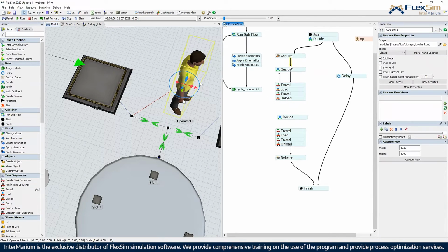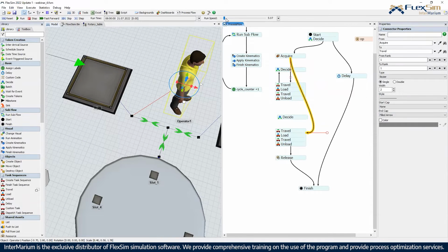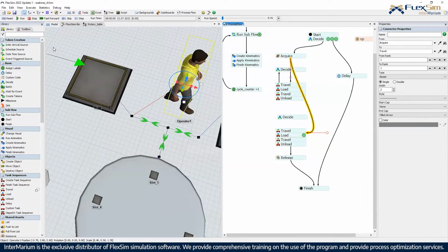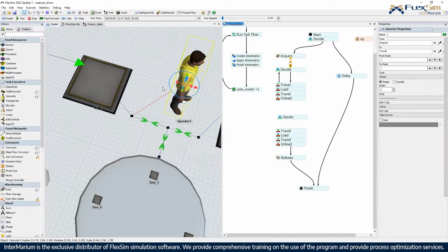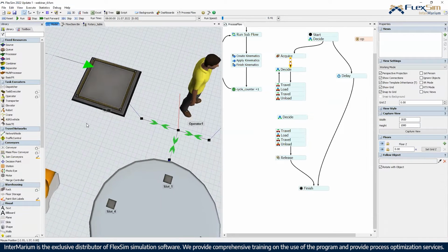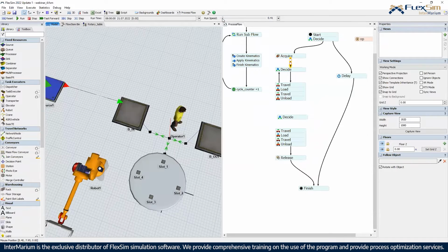Why? Because FlexSim assumes that operator is already there and this logic runs faster than the model. So this is first before the simulation. So when I run this logic, when token goes to this load, I still don't have product on the queue. So that's why we have to change. It didn't work like this before because then he needs to travel, and after he travels he checks, and in this case, the product will have some time to be on the queue. Okay.